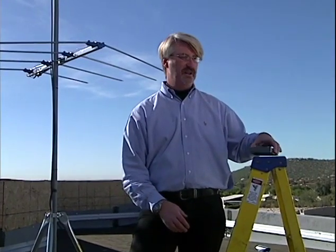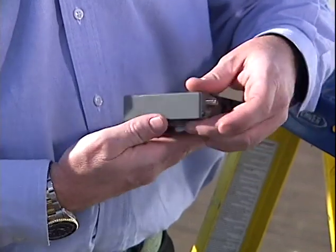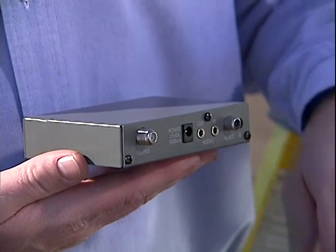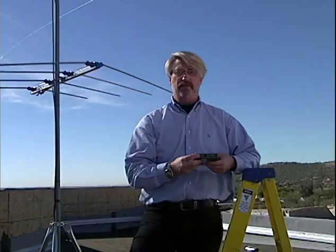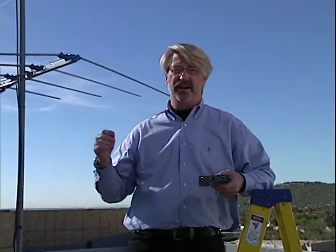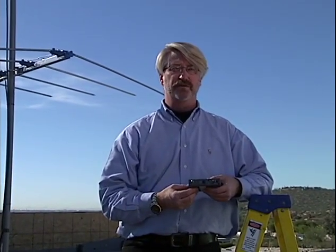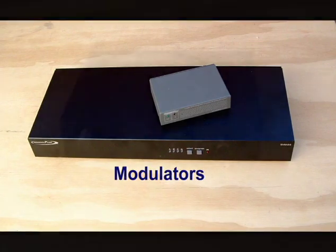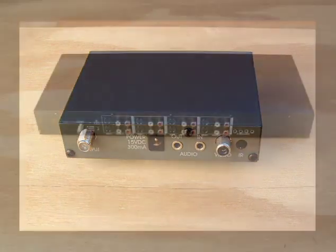Modulators are like very small television stations that broadcast a baseband audio and video source onto a cable or off-air television channel. They have a baseband audio and video input and an F-connector RF output. You could hook the output of a modulator directly up to an off-air antenna and operate your own television station for your neighborhood. If no one complains, you might get away with it for a while, but remember, it is illegal.